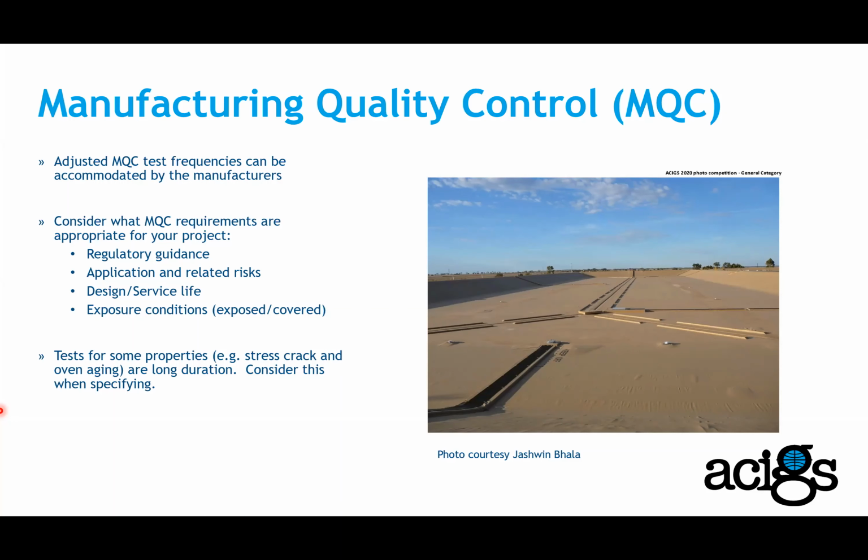Tests for some properties, for example, stress crack and oven aging, are long duration testings. So when we specify material to meet certain criteria in terms of stress crack or oven aging or any other long duration testing, we need to consider the time period that is required for that test.